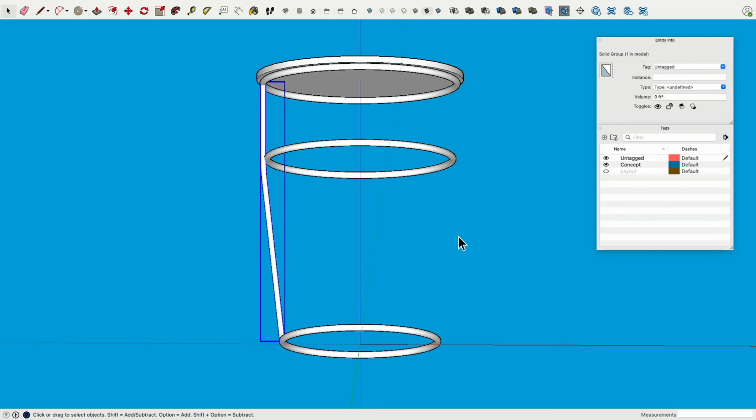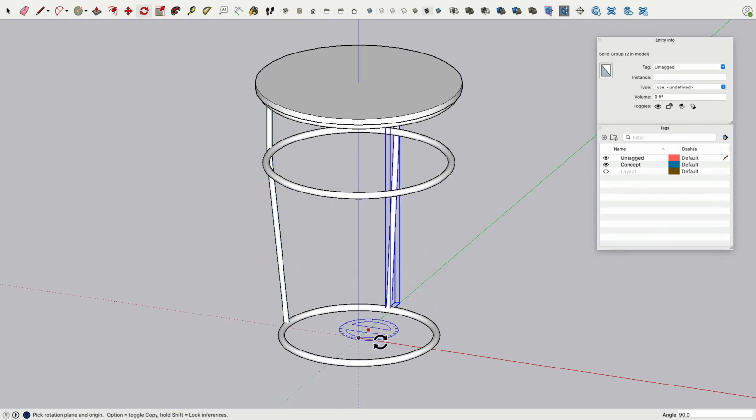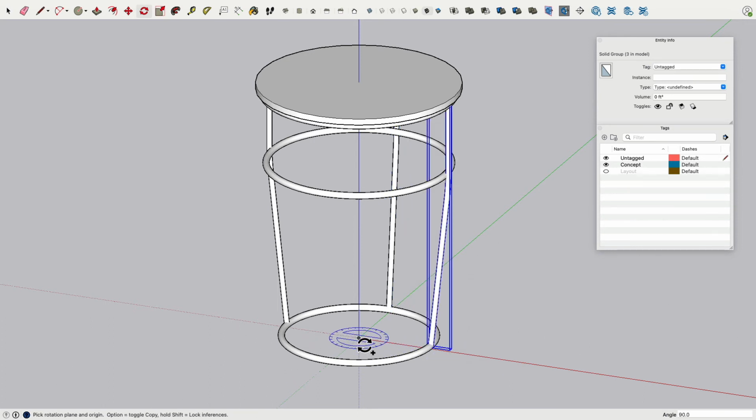To create multiple copies rotated along here, we can actually use the rotate command. And while we use the rotate command, turn on the copy function. So I press the Alt Option key, click, and you see that it has then a plus icon, center of rotation, start of rotation, end of rotation. Let's do this one more time. Okay, see? Super easy.